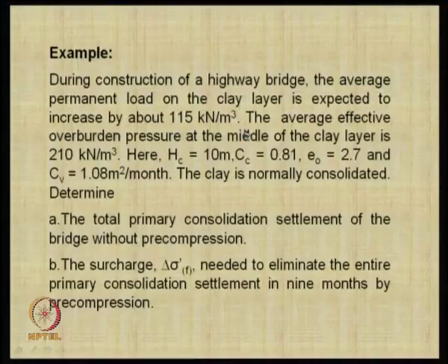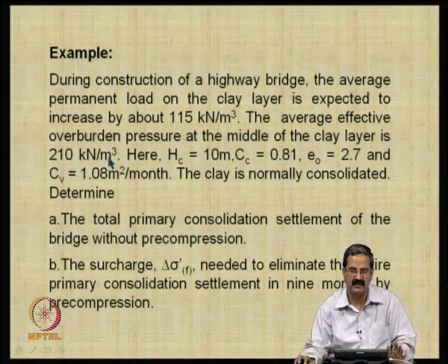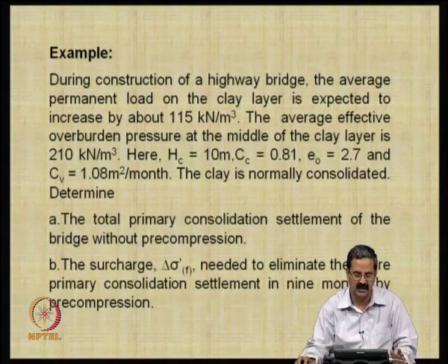What is the extra stress because of the embankment construction of 5 meters? It could be very high, but as you go down, the additional stress that you can expect from the load is less. Sometimes we say twice the breadth, like the pressure bulb, all those concepts we know. Essentially we would like to see that this loading is taken care of. In this case, for the depth, this is a simple illustrative example; one should do it very systematically, and there are some programs available.